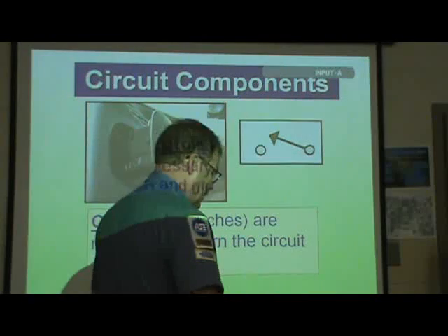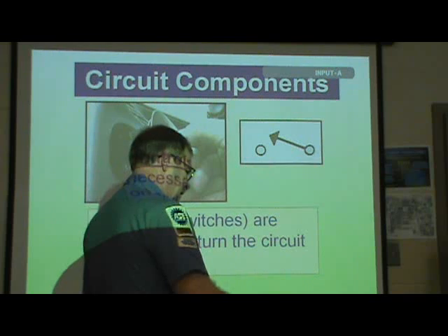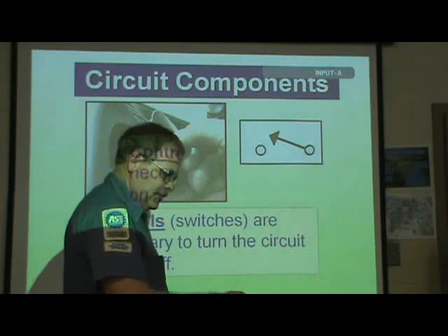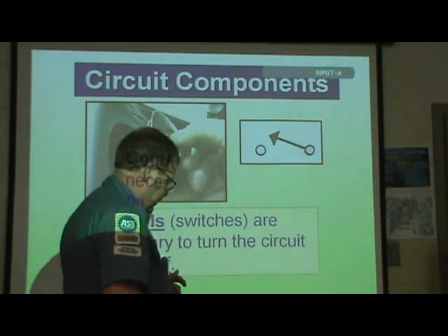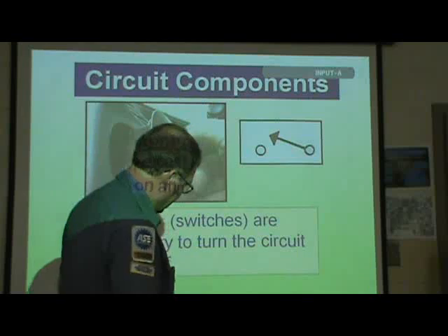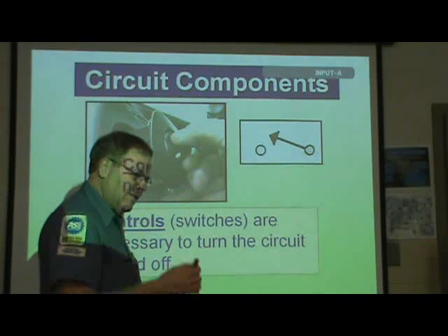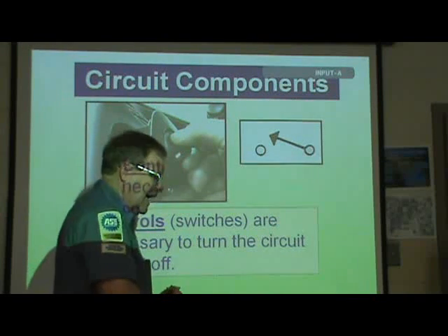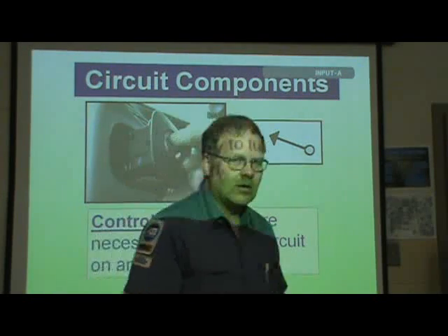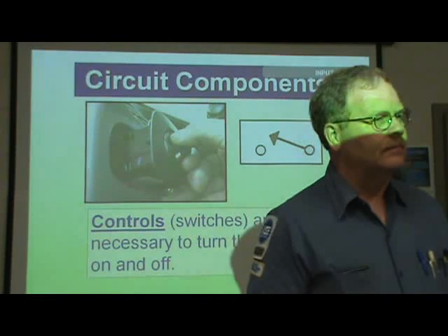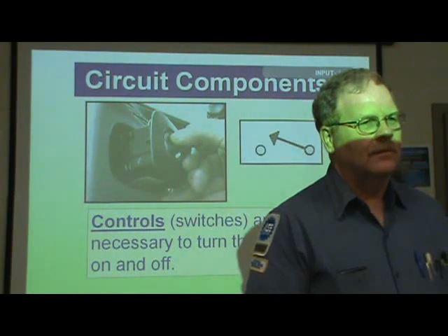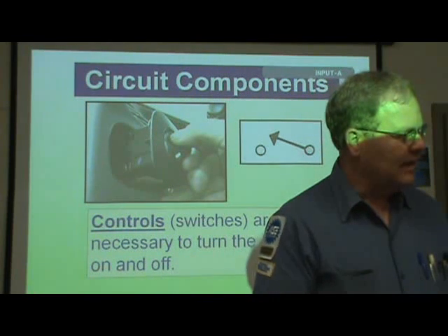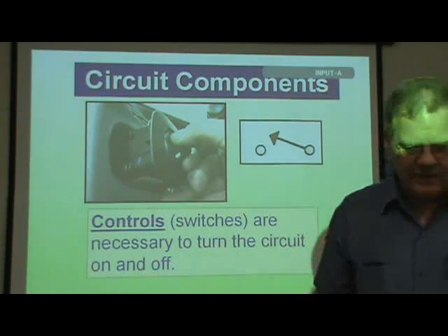So then I hook up to the negative side of the battery. You got it? And then we turn the key and I hear a click on the starter relay, but nothing really happens as far as this engine spinning over. And I touch this, and the light lights up. Now I'm hooked to the negative side of the battery, and I'm touching this metal on the engine, and this light lights up really bright. What's wrong? It isn't grounded. The engine block is not grounded to the battery. You'd be surprised how often you see stuff like that. And how do you know it's not grounded?